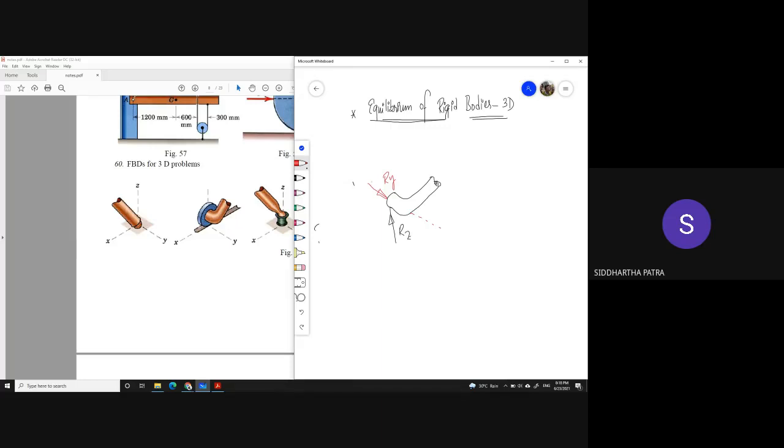Because in order to do so, the wheel would have to be misaligned with the channel. Do you think the object can rotate about the z-axis? No, sir. I think it cannot rotate. So I would be experiencing a reaction moment in the z direction.